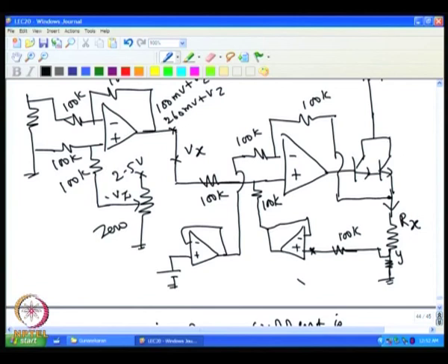By connecting this output, you will get this required voltage, which can also be varied by varying this resistor. So, any voltage you want, because you have a 2.5 volt zener here. Whatever voltage you need can be tapped by varying these two resistors.